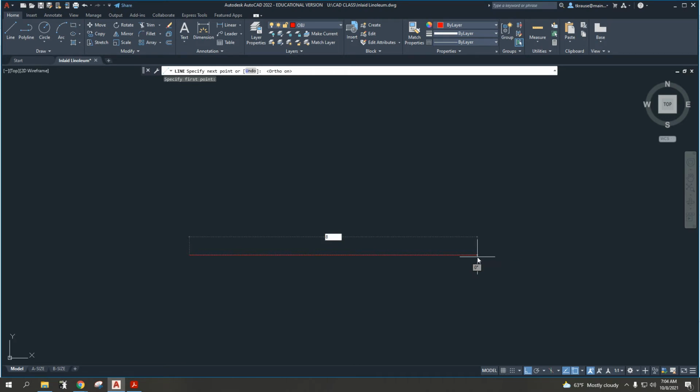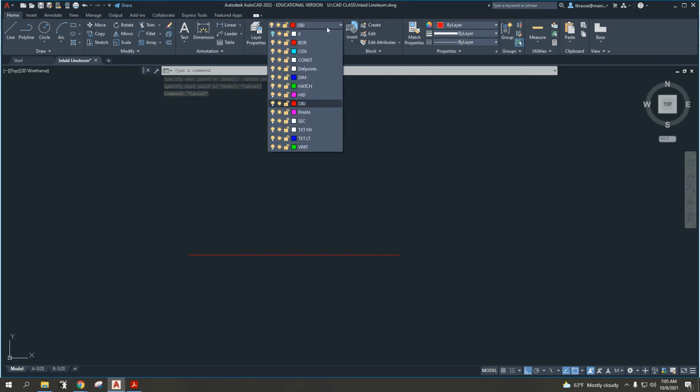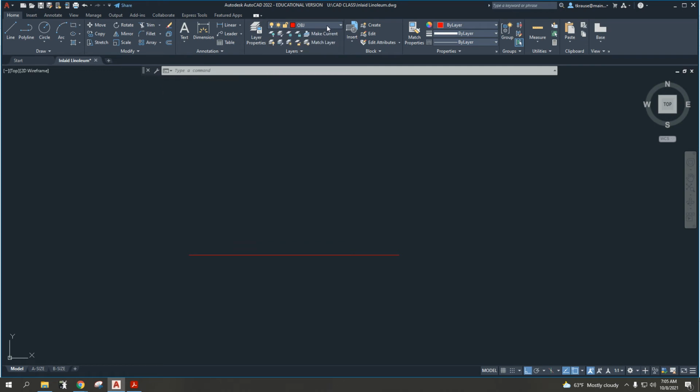Okay. I just typed 8. You'll see now that blue highlighted area is turned to an 8 rather than whatever I drag out. And I'm going to hit enter on my keyboard. And you'll see right there, I should have now drawn an 8" line. Okay, notice I am on the object layer. That's where I want to be, at least for now.